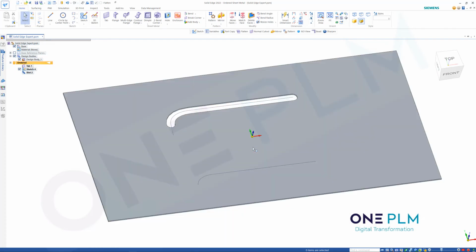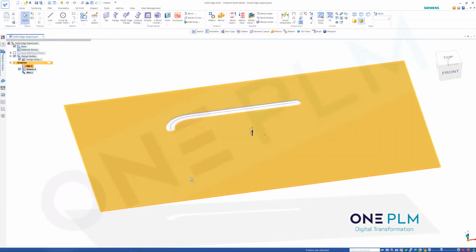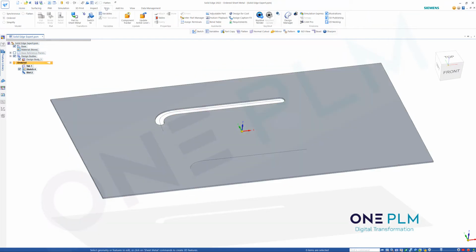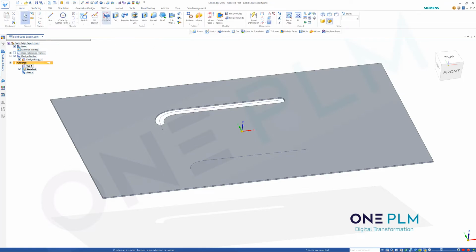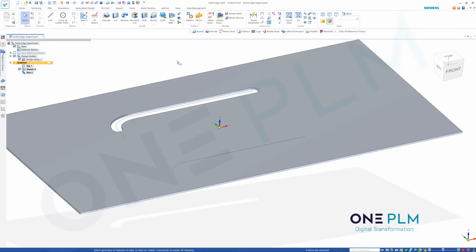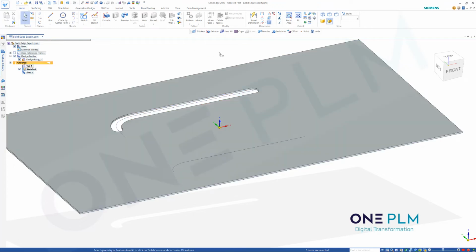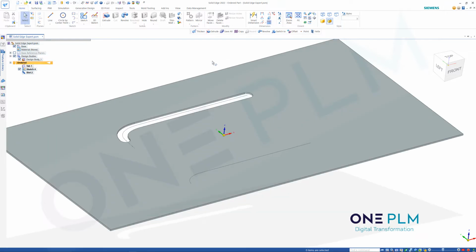Okay, the second option we can do is use multi-body modeling. So we can create a tool. I can create a cutting tool, which we're going to use for this. So for this, I'm going to go to tools and switch to the part environment, and I'm just going to create a cylinder. It's easier if we do that in the part environment. Before we create this, we're going to make sure that we add this as a design body. If you do forget to do that, you will have to go back and redo it. There may be an option later in a newer version where we can do that at the end, which will be nice. Fingers crossed that we get that.